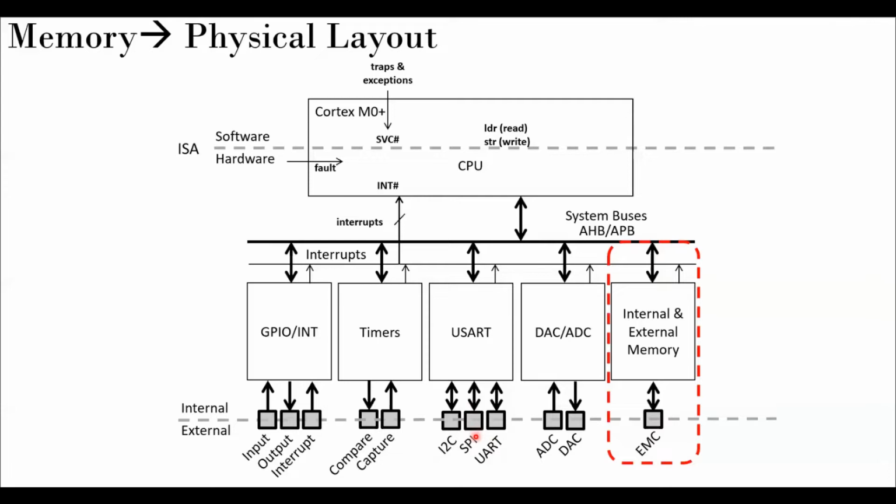It is a synchronous system, of course, so there is one dedicated clock line, then one for data transmission, one for reception. So it is a full duplex system. And then, of course, one for the chip select or the slave select. Those are the 4 pins. If you have multiple slaves, we have more slave select wires. That means a 4+ wire system, correct? And then, last but not least, this is the most magnificent serial communication system, I would say, I2C, the integrated circuit bus popularized by NXP or earlier Philips. This is again a two-line system, one for clock, one for data.